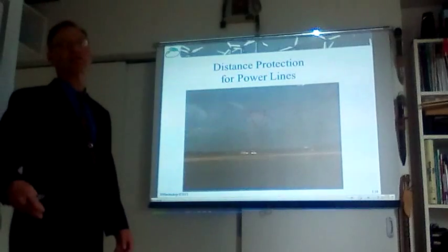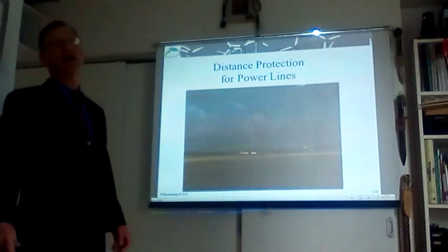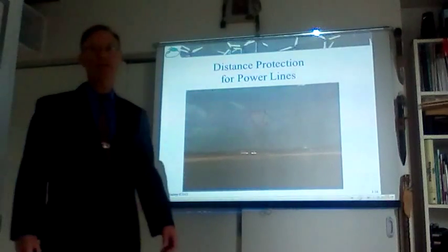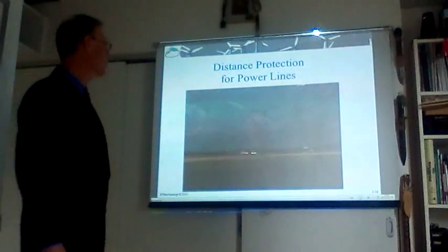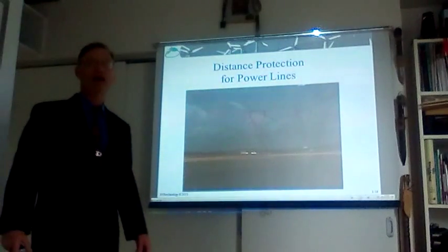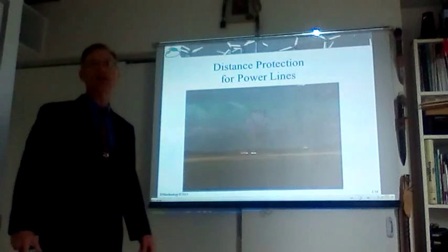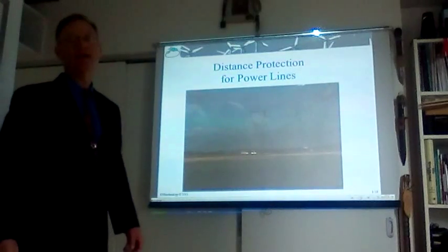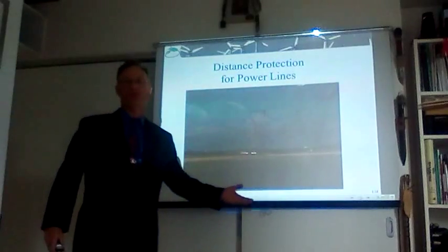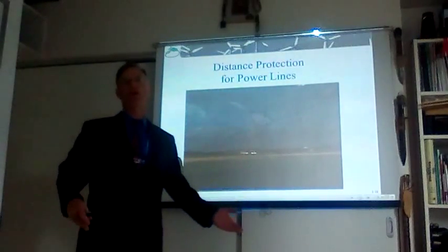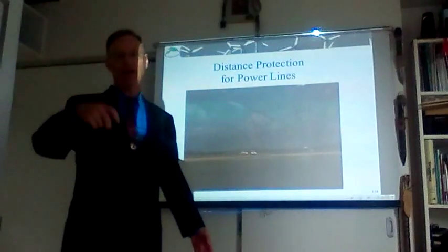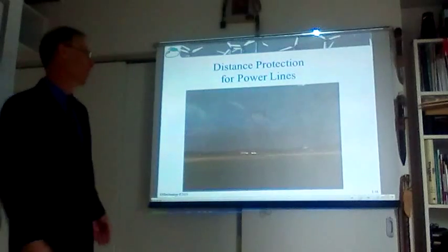So we are talking about 138 kV, 163 kV, 250 kV, and so on. In North America, it's quite common to use 500 kV, but that depends on the length of the line. The longer the line, the more losses we have, and therefore we will upgrade the voltage higher and higher to cover for those losses.